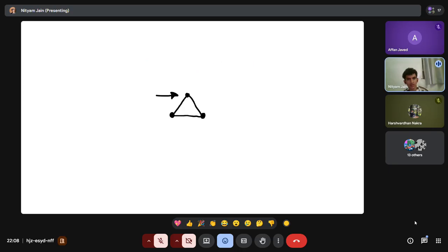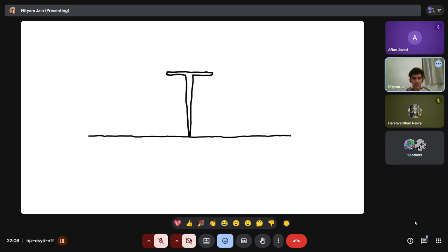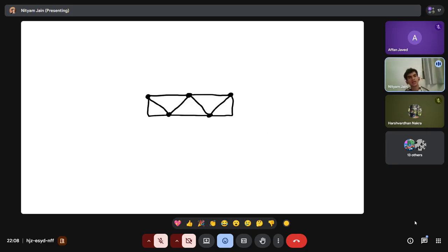And just to see, in a triangle, usually if you have three pin joints, there can be no movement because it cannot form a parallelogram. Basically, a triangle cannot be deformed. It's the strongest form. And on that logic, triangulation allows bending to turn into pure axial forces. And in any truss, as I'm saying, it can be pin joints.